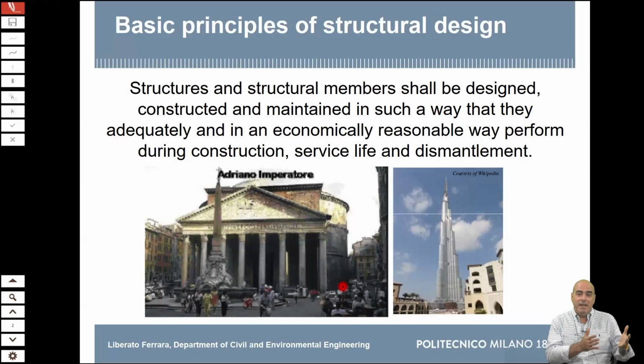So the durability of that material is because it has been employed in such a way that it's compressed, there is no reinforcement, and the exposure condition is such that it does not harm the characteristics of the material. So this is always what you have to take into account.